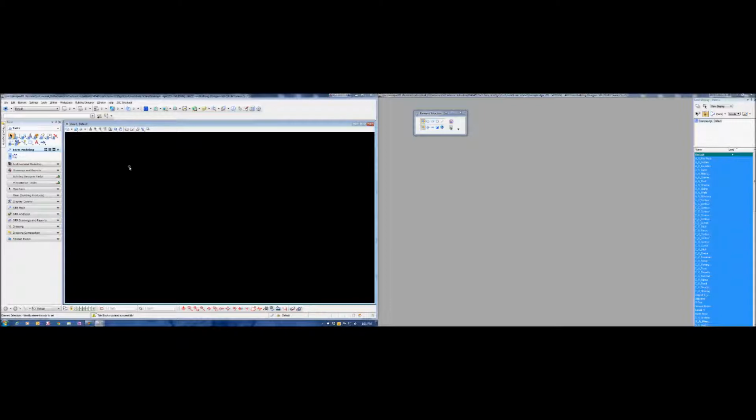Okay, so once your file is open, first thing that you're going to want to do is come down and go to Model. So this is going to be where you reference in all your extraction information and anything that you want to draw, sections, details, anything you want to draw manually. This is where it's going to go. Any annotation that's going to be on the model or on the drawing is going to be under default.